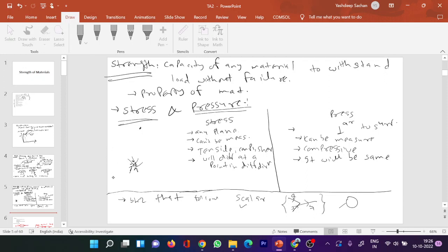So at that time you are applying pressure, then stress would be there. It is a completely rigid body, they told. Yes sir. Sir, if it's a rigid body, then Young's modulus will be infinite, and the stress will be infinite. So deformation we can say would be zero, because it is rigid, so E would be infinite, and in PL by AE the deflection would be zero. Means any deformation would be zero, but stress would be there.